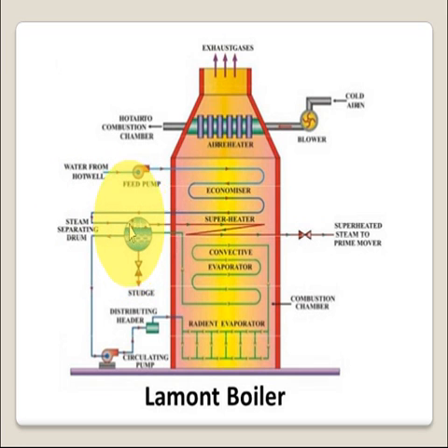From steam separating drum, this hot water is supplied into radiant evaporator with the help of this circulating pump. In radiant evaporator, we have two header lines and different tubes through which water flows and gains the heat by radiation. That's why the evaporator is known as radiant evaporator.